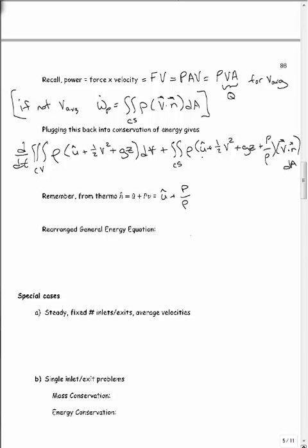Okay, so this term here plus this term here is just h. Again, I put a little cap over h because we have HFs and HSs that we're using here in fluids. And that's all because little v equals 1 over rho, specific volume. Okay, so if you rearrange that then, you're going to get your equation with h's.